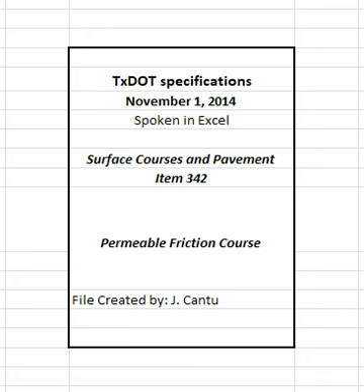4.9.6 Irregularities. Identify and correct irregularities, including segregation, rutting, raveling, flushing, fat spots, mat slippage, irregular color, irregular texture, roller marks, tears, gouges, streaks, uncoated aggregate particles, or broken aggregate particles. The engineer may also identify irregularities, and in such cases, the engineer will promptly notify the contractor.